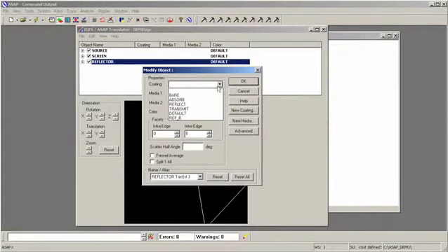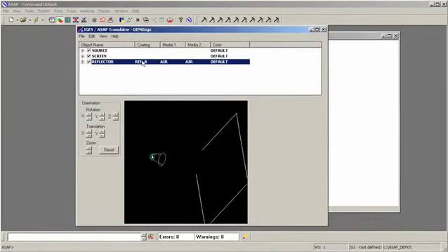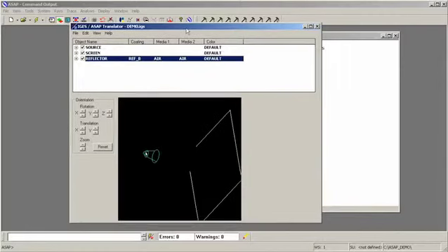Okay, and then right here under coatings, I'm going to specify the coating that I just defined. Media 1, media 2 will be air. Click OK, and the changes I just made to the reflector are displayed right here. Now, with a more complex optical system, you would be repeating this process many times, specifying new coatings, specifying new materials, glass types, for instance. Or for this very simple system, that's all we need to do.